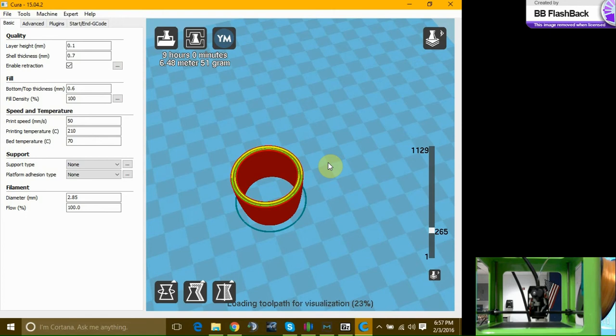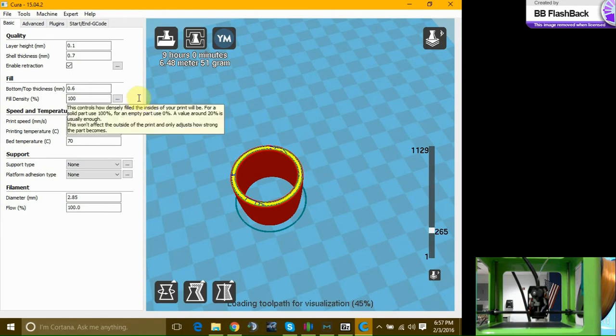This is so it gives a 100% fill for the top and bottom if you don't have 100% fill density or a certain number fill density. So it gives you the solid look, just like the cube, you have equal layer to wall ratio, how I printed those. Fill density, we already went over fill density.